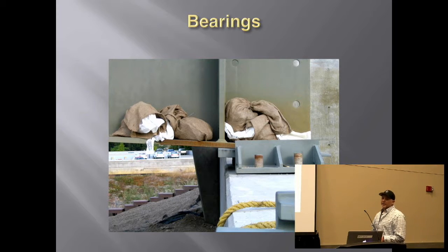And we start asking them to pick up the pads, move them, clean them off, and also wipe the bottom of the girders off, and the guys get a little excited about it. But unfortunately, if they don't do that, the gravel and all the debris underneath those bearings will eventually wear through the bearing surfaces, and the bearings will fail.